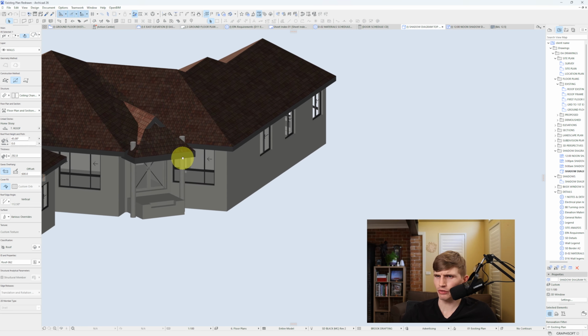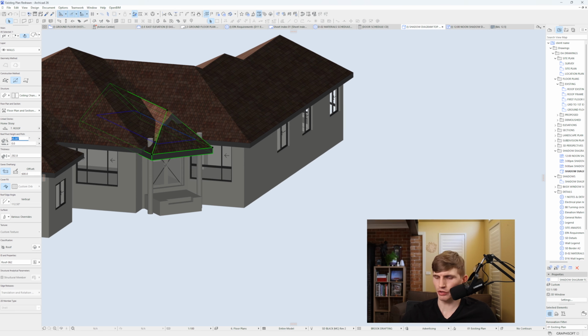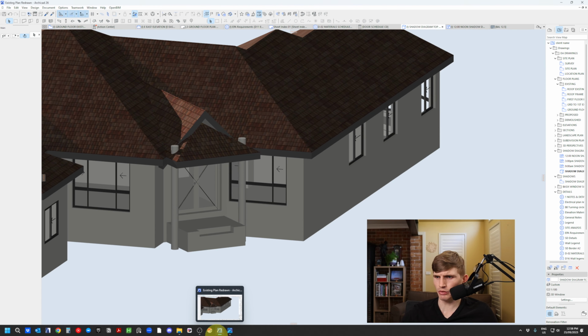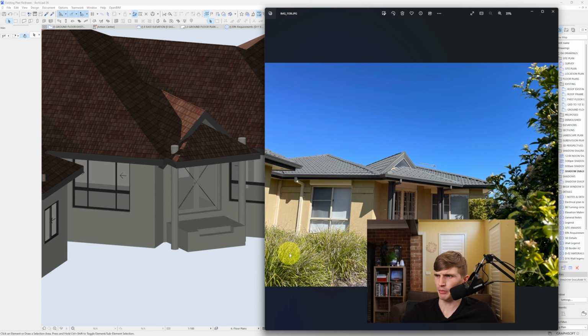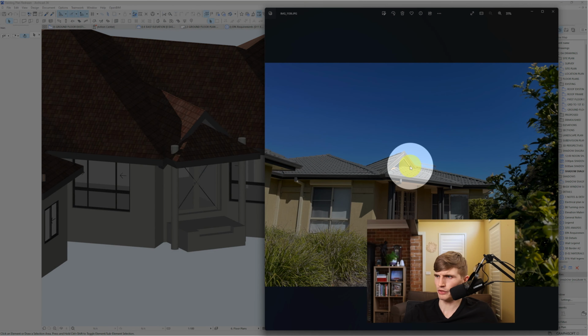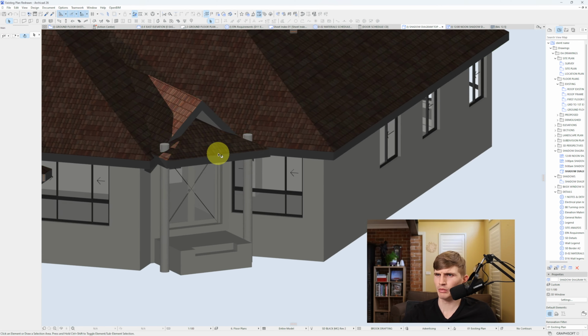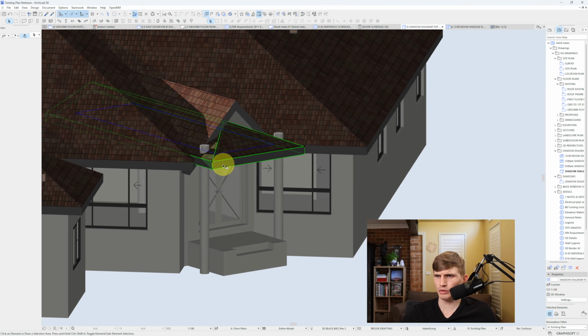Now the roof pitch on this is way too high there at the moment, so let's change this back to say a 30-degree pitch, and we'll keep those roof planes custom and see how we look compared to our reference. Getting much, much closer. Now, just looking at these roof pitches, it's a shallower roof pitch than say this one here. So I dare say this has probably been bumped down to something along the lines of about 20, maybe 22.5. So let's go back in, change this to say 22.5. Keep the planes custom, and that's pretty well good.